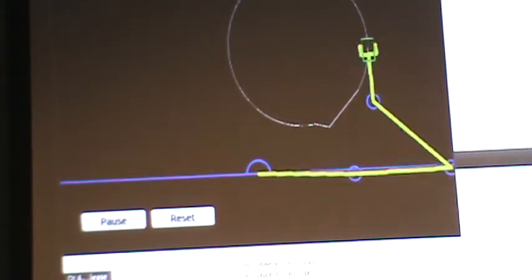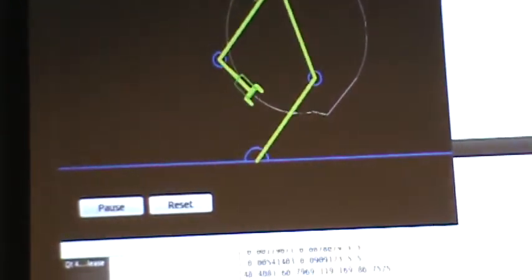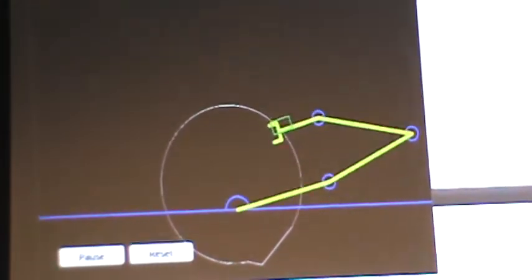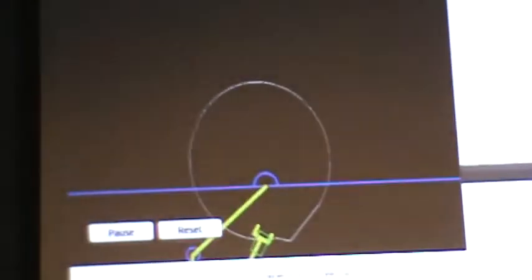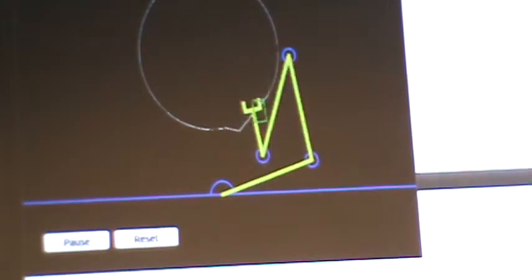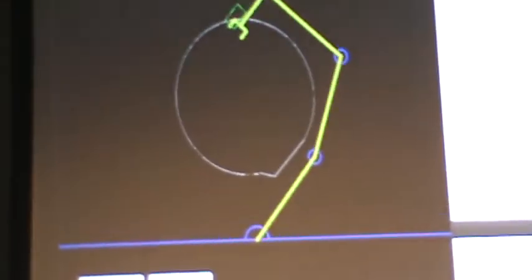As you can see, sometimes it's not able to track this. The reason is that we have joint limits on this robot, because it cannot move 360. Let's say I ask, can you go from 180 degrees to 360? You can't do that. You would hit yourself a lot of times unless you design a way that it doesn't hit. There are robots that do that, for example for the volumetrics. But this robot has joint limits of 30 degrees on each side, so I only have 300 degrees to work with. That poses a problem.